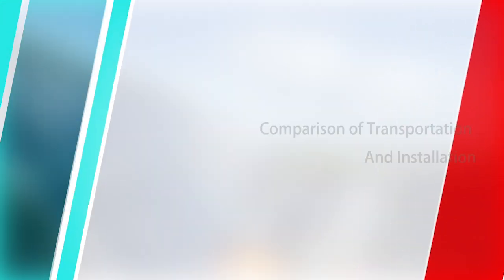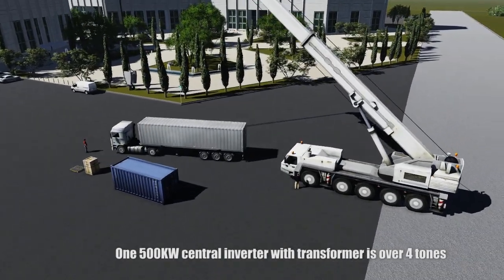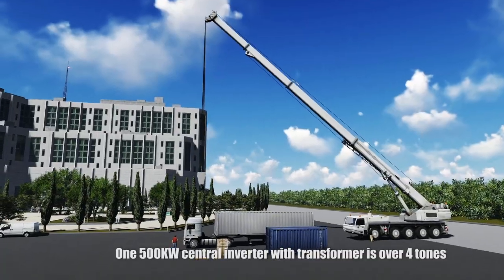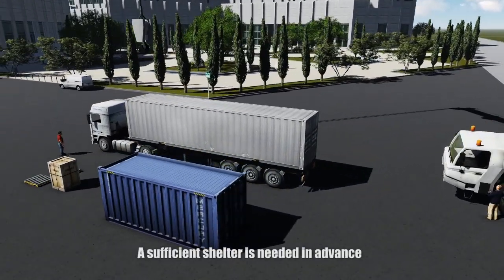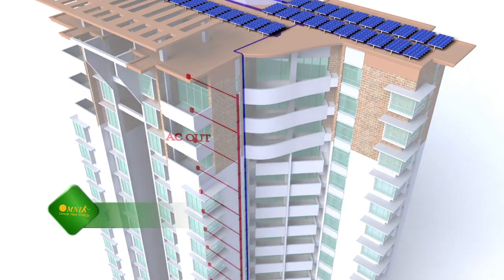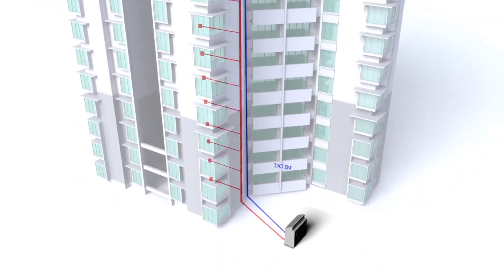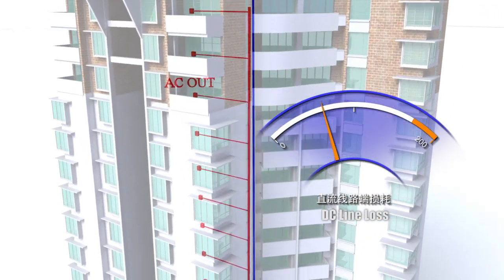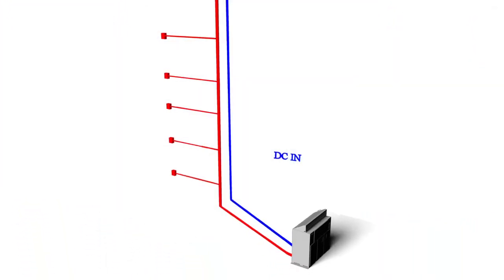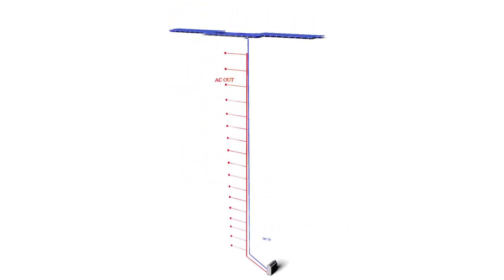Easy transportation and installation. One 500 kilowatt central inverter with transformer is over 4 tons. A sufficient shelter is needed in advance. For decentralized applications, all cables need to be combined at the rooftop, then connected with the inverter and transmitted to the consumer side. AC current could be up to several hundred amperes. Wiring is complex and dangerous. Transportation cost is high, as well as the DC wiring cost and line loss.